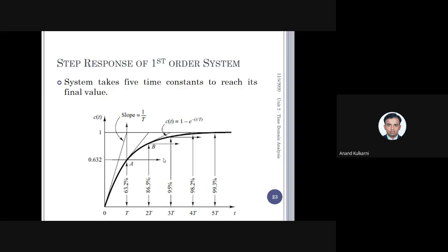Same thing is with the pressure measuring device also. You have a manometer, you have a Bourdon tube pressure gauge, you have diaphragm type strain gauge mounted pressure sensors. So each one has different response times. So depending on your application, unless you analyze that, you will not know which one has to be used. If the data is changing fast, then it should have a low time constant. If the data is changing slowly, then you can afford to have a large time constant. Not much error will be observed.